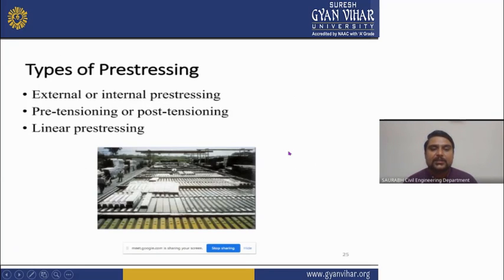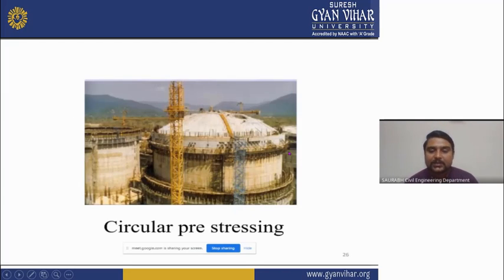Types of prestressing: external or internal prestressing, pre-tensioning and post-tensioning, and one more is linear prestressing. These are the types of prestressing which are used in the casting of PSC members. Now we will see circular prestressing.